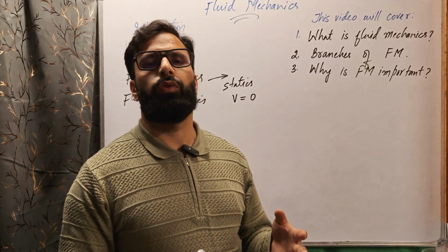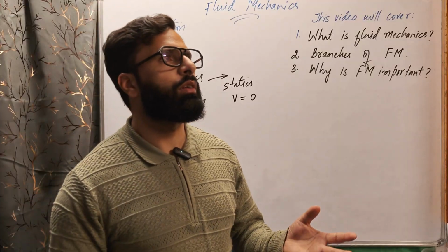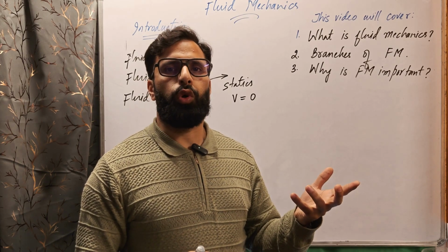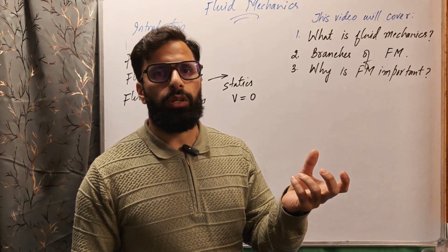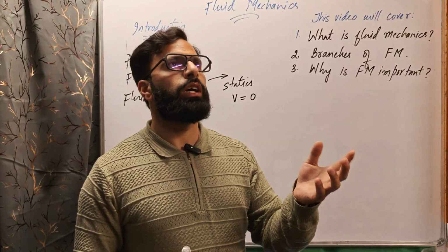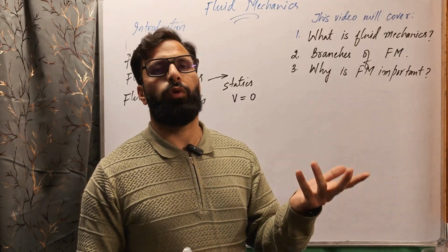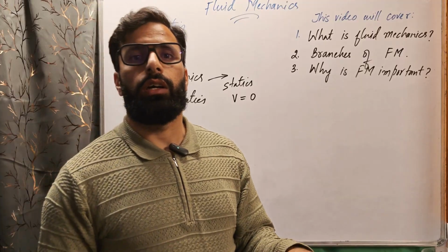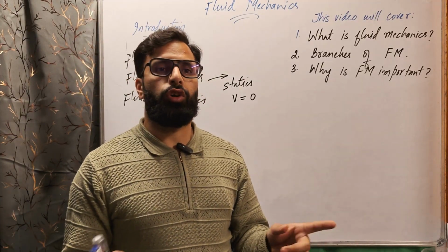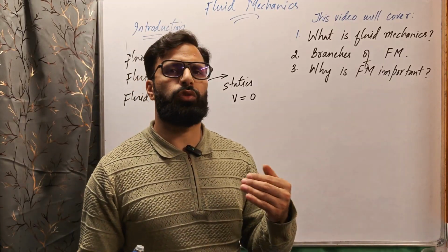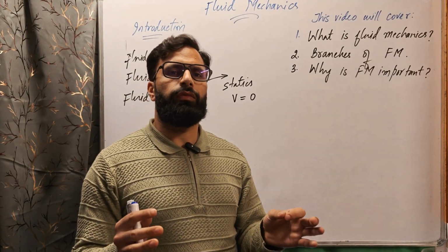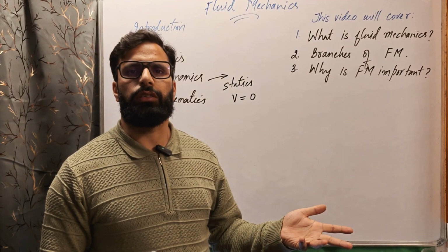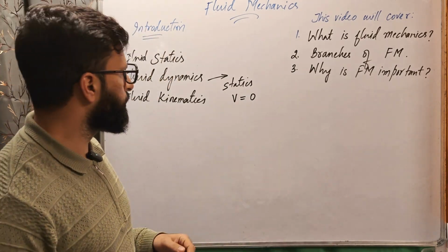In this, we study various fluid flow visualizations. For example, how the air is flowing in this room, what are the air patterns? We can generate smoke, and since air is invisible, the flow pattern of the smoke will tell us the flow pattern of the air. These flow visualization techniques study only the velocity, the acceleration, the displacement, not worrying about the forces that cause those velocity changes or accelerations. When we are only concerned about the description, the velocity, the acceleration, the flow patterns, we call it fluid kinematics.